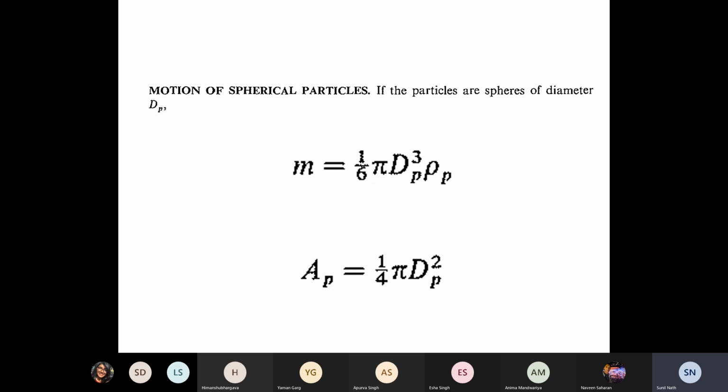So next week, I would like to take that up. And as I have repeatedly said, if you were to just not look at the hydrodynamic regime, you will underestimate or overestimate the drag force by orders of magnitude. For instance, if the Reynolds number were 10 to the power minus 5, and you want to go to 10 to the power plus 5, which is the 10 decades of range that I want to take up, over the 10 decades of Reynolds number, the drag force will change by, let us say, 5 orders of magnitude.